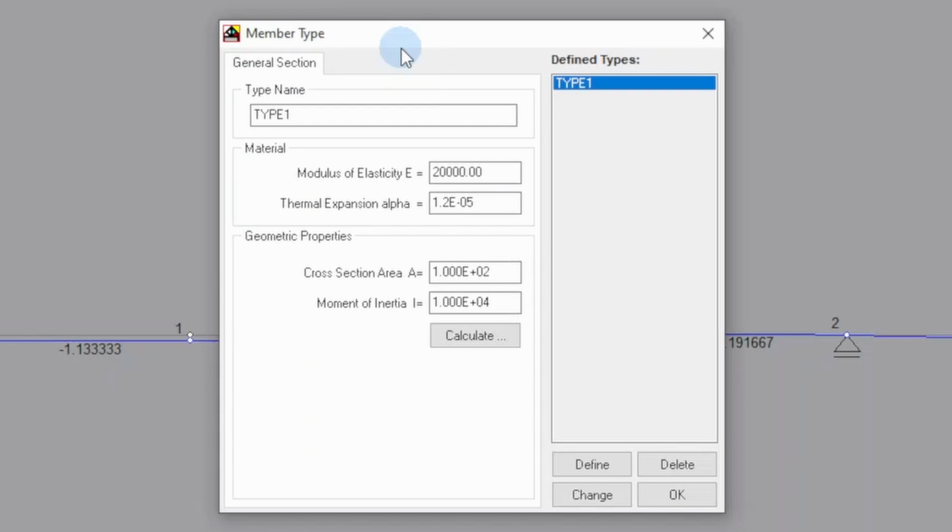If you recognise the modulus of elasticity as being that of steel, then well done. Values of 20,500 and 20,700 kilonewtons per centimetre squared are also often used, and usually they're stated as 205 and 207 kilonewtons per millimetre squared. Dr. Jim also dimly remembers the coefficient of thermal expansion for steel to be 11 times 10 to the minus 6, and that pretty well confirms that the default LinPro elements are made from steel.